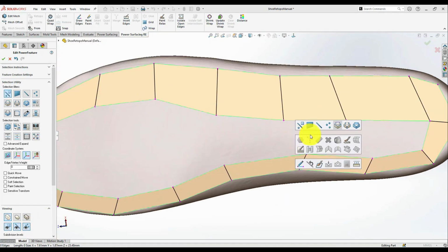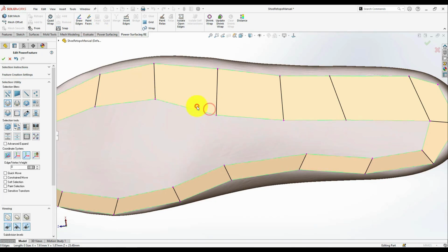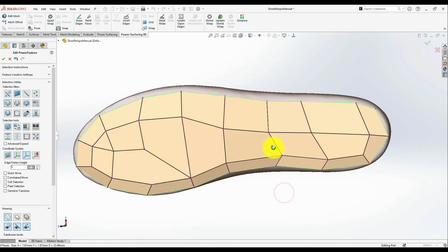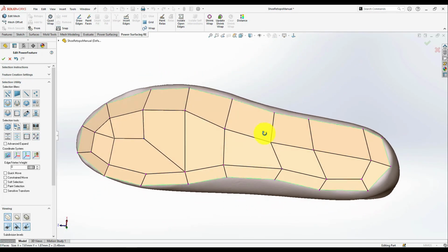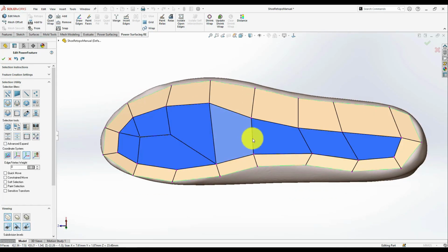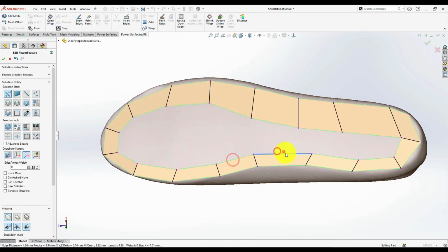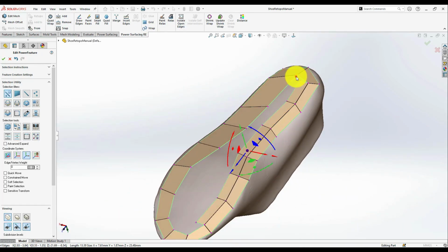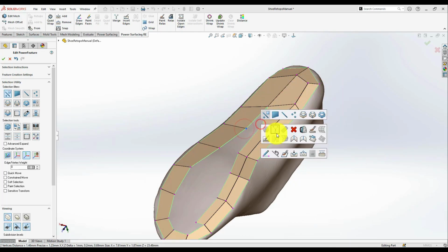I can close this by just quad wrapping or manually. Let's try both and see which one is going to be better. So first, the quad wrapping: by pressing on here, you have a fully closed mesh, and I think it looks good. And the other way is just to reconnect it manually. It gives you the ability to just change the topology look. Here and here.